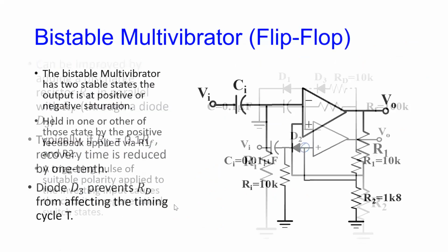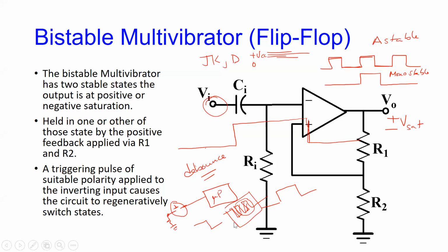So once the bouncing of the switch is occurring in this zone here, all of these other positive and negative incursions are ignored. So when you press the switch, you get a nice clean single pulse that the microprocessor will now use to reset or to detect some sort of input and do whatever it has to do.